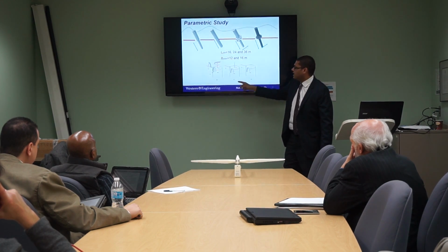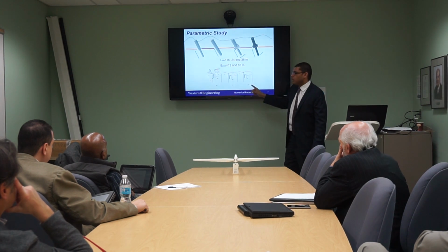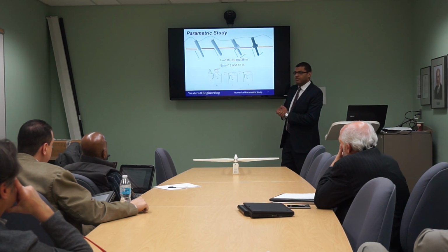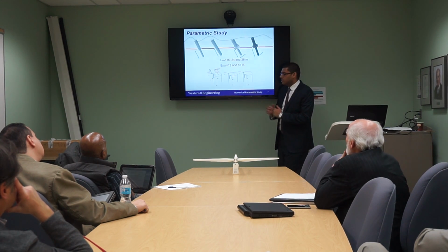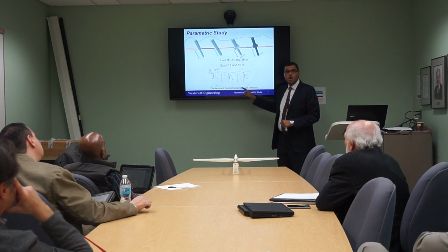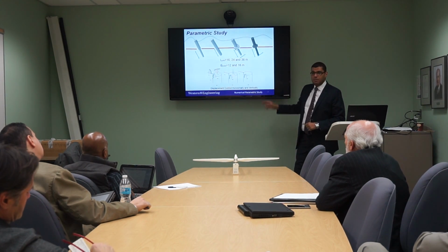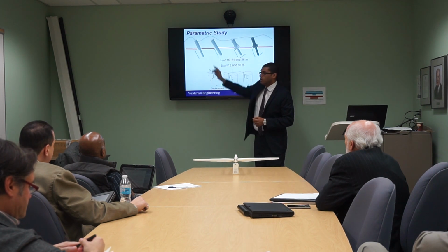Then we have done our analysis with 3 components, just vertical, horizontal, and moment, and then 2 components, as most studies in foundation design use just 2 components from the wind loads. We have also done displacement control horizontally and vertically to be able to get the actual capacity of the system. This has been done for different foundation systems.